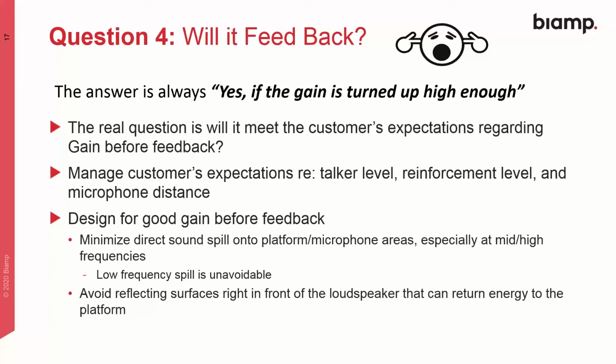You can aid the situation in some respects by designing for good gain before feedback. Minimize direct sound fill to the platform and microphone areas, especially at mid-high frequencies. Low frequency spill is kind of unavoidable, but if you need to push the gain, you've got a quiet talker or something, the sound operator can always roll off the low frequencies and kind of get around that.